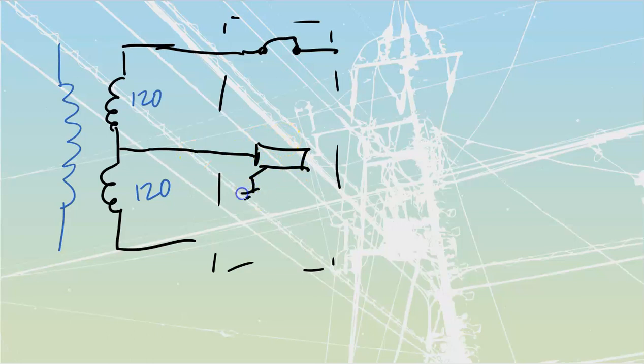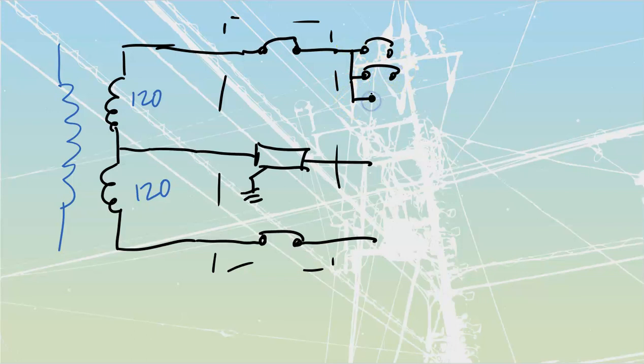That neutral is going to get grounded down. And then on my line 2, we get the same thing. We get our main circuit breaker. And then from there, my circuit breaker goes down to the subdistribution. And from the subdistribution goes out to all the rest of the loads. So we'll have our individual panel breakers that are going to be inside of there. These are going to be like the 50 amp, the 20 amp, etc. Those are going to be fed out to a bunch of different types of loads. That's the stuff that we're trying to protect.